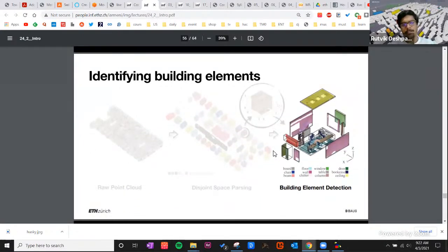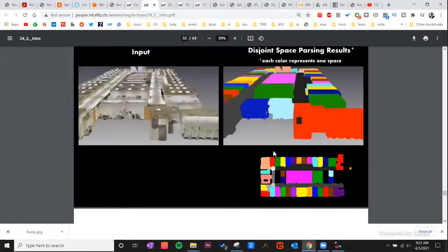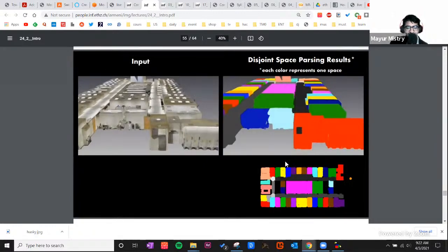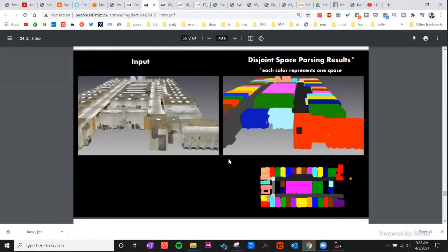One way I can think it can be done automatically is if we have the building model in Revit, we know the dimension of the room in geo location, and then when we get the point cloud, I can do some automation that if all the points lie in this bounding box, assign this room.